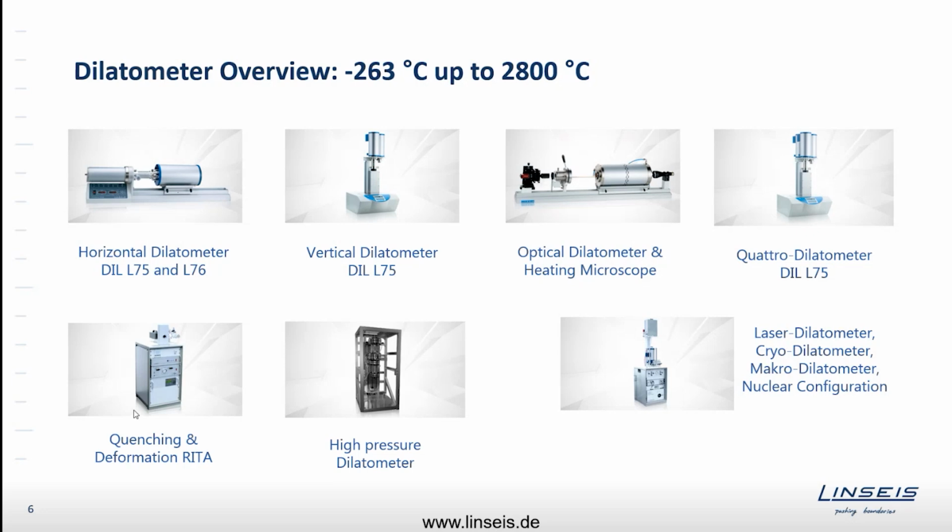And then we have dilatometers for special applications, like the quenching and deformation series. We call it RITA for rapid inductive thermal analysis. It's an inductive dilatometer for the steel industries. It can heat up metal, or especially steel samples, very quickly and simulate a forging process or simulate a firing process. You can reach 1,000 or 2,000 centigrades within seconds here, and you can also cool it quite fast within seconds using helium, expanding helium gas. And therefore you can create phase diagrams and 3D phase diagrams of steel phases and of different metal phases. So it's something very special, but quite useful. Then on the next picture, we have a pressure dilatometer.